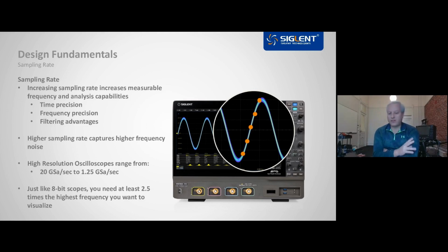One downside here is that higher frequency sampling will capture and display higher bandwidth noise. It's also true of higher actual bandwidth. A higher bandwidth scope with the same sampling could alias on high bandwidth noise, creating some noise artifacts for us.